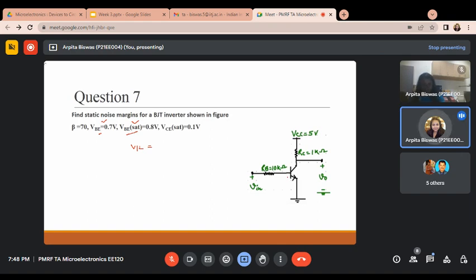And when you are calculating the VIH, you are giving the higher input voltage. In that case, what is the value of VBE? 0.8. Yes, in that case, you have to take VBE equal to 0.8. Now calculate using the same loop. This is the loop. You have to just take this loop. First case, when you calculate the VIL, just take the VBE value 0.7, and when you are giving the V input high, in that case, VBE saturation, 0.8. Simply you have to do this.